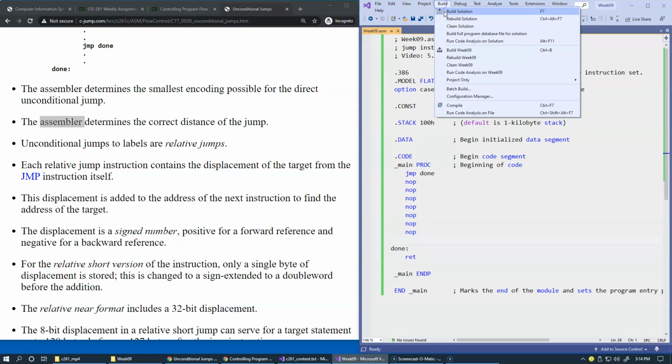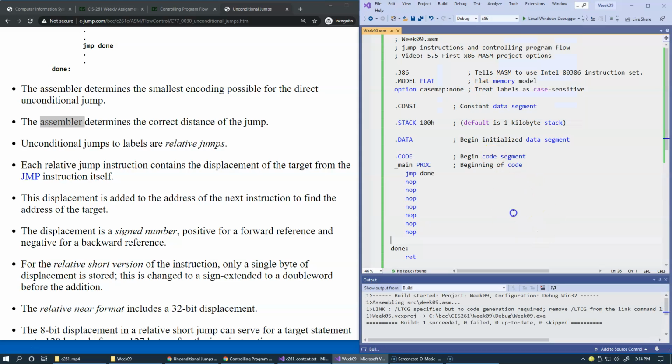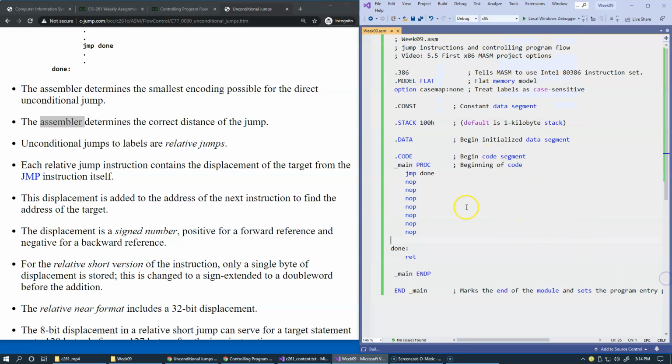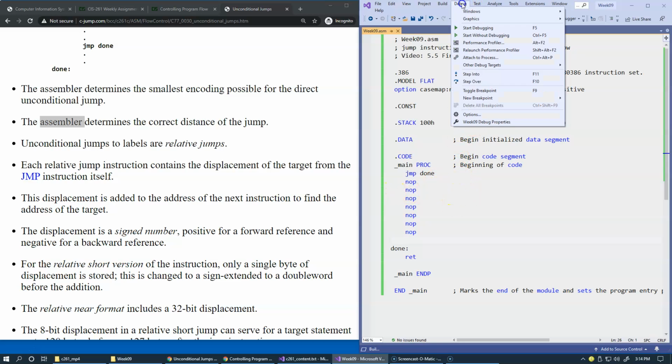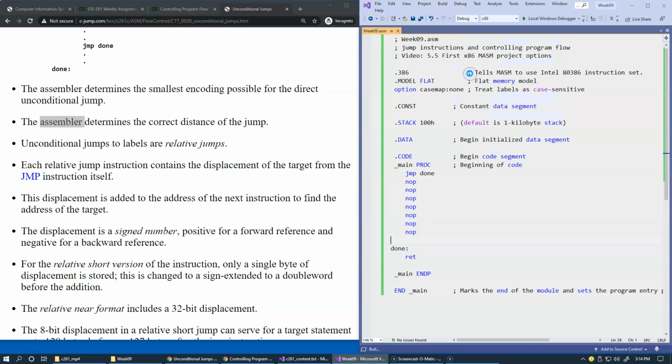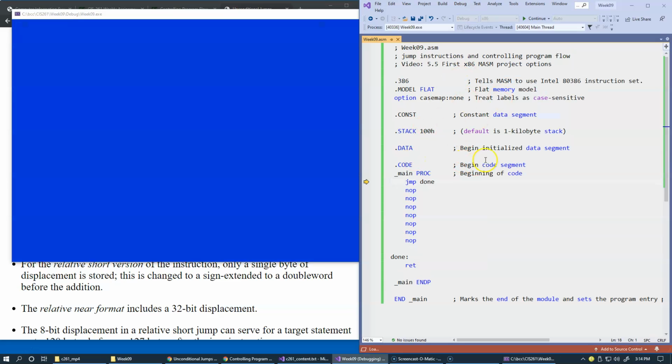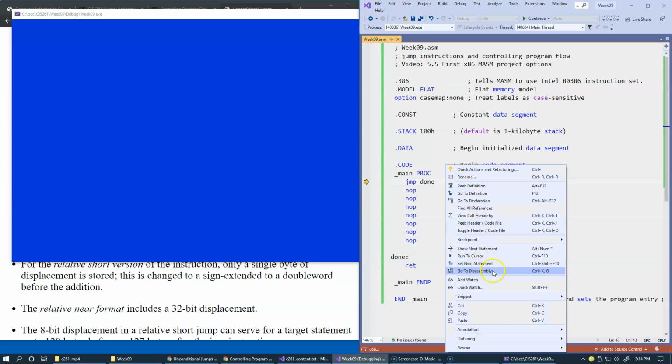And so let's now build. So again, this is just a do-nothing program that looks like this. And what we can do is, for instance, say step into, which will stop on the first instruction that belongs to our application code, like this. And so right now it's just started. You can see that it's telling me that it's just about to start executing this instruction. Of course, it may be a little bit more interesting to peek into disassembly.